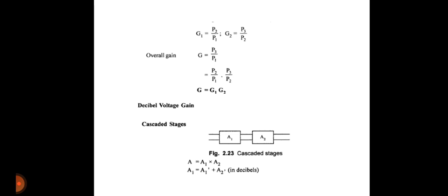Actually, the output of an amplifier is fed to a loudspeaker to produce sound which can be heard by the human ear. The ear responds to sound intensities on a logarithmic scale rather than a linear scale. So the use of dB is very important for representation of amplifier gains. That is why gain should always be represented in dB.